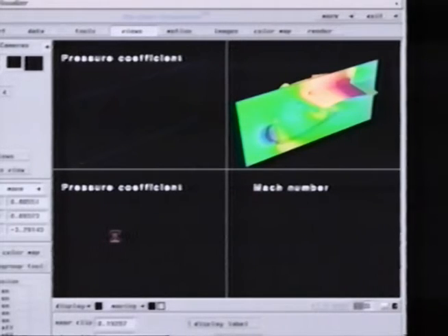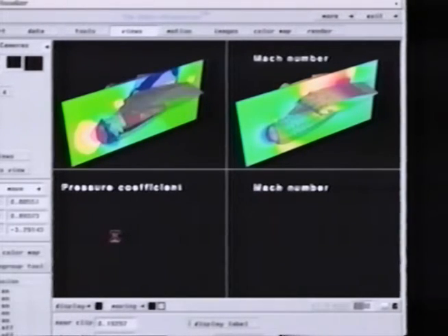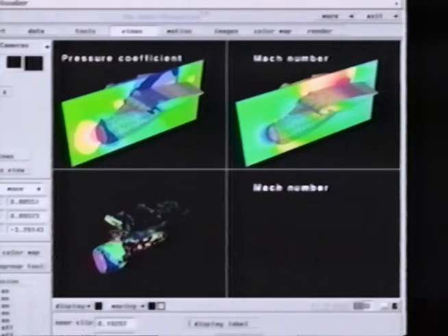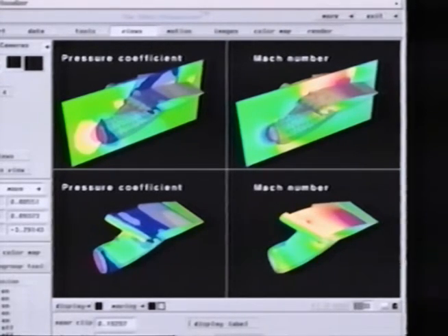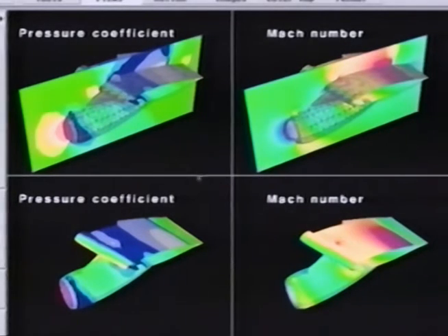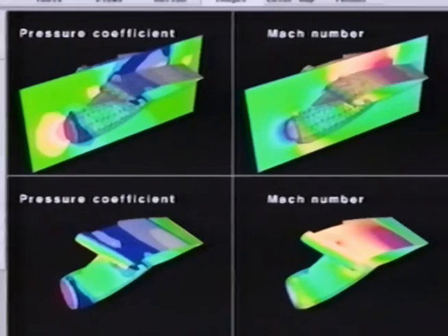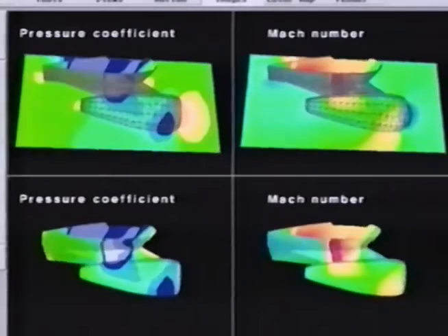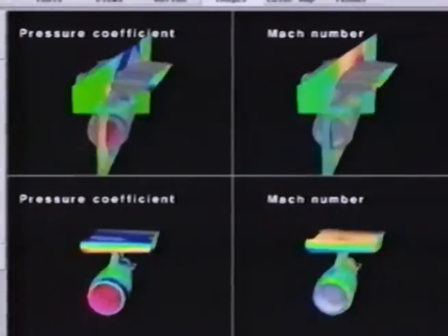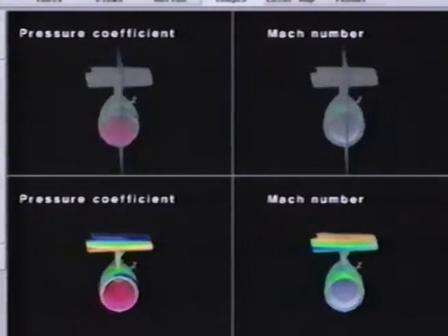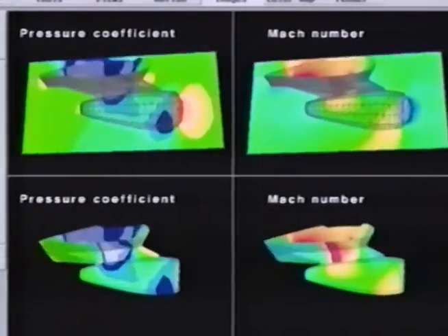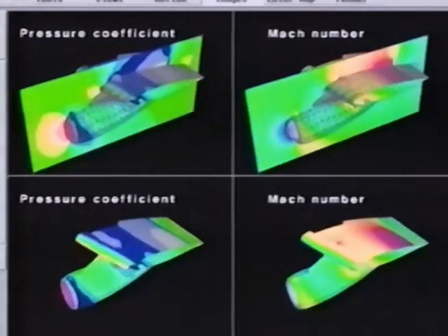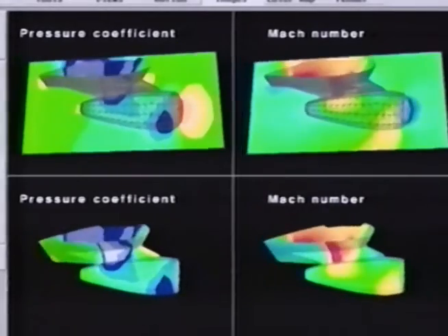The vantage point provided by the perspective camera is duplicated in all 4 views. Each of those views, however, sees a different collection of tools. Since tools are attached to data, each can be used to represent a different property. In this case, upper right depicts Mach number both on the bounding geometry and in the surrounding flow field. Surface mesh wireframe is overlaid as well. The upper left viewport duplicates this collection of tools, but the tools are attached instead to pressure coefficient. In the bottom right and left views, no off-body data is displayed and the surface mesh wireframe is deleted.